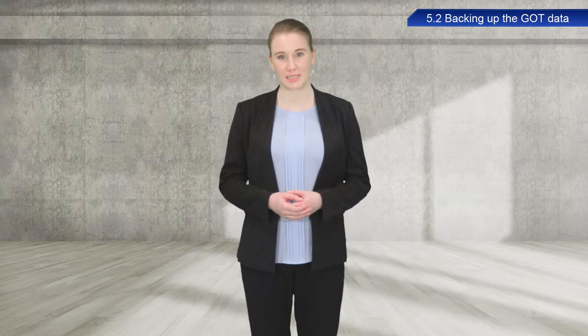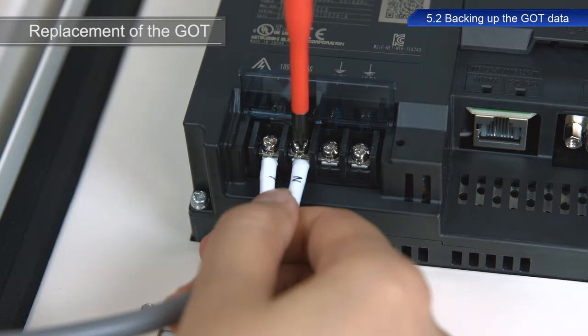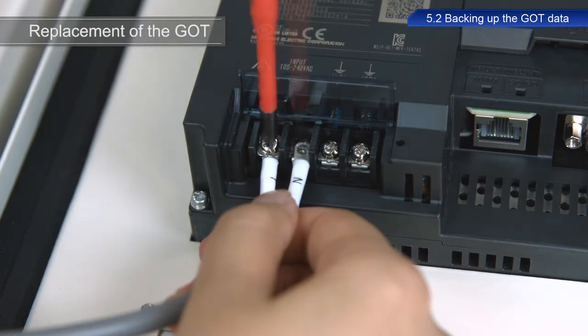Let's now replace the GOT, assuming that some accident has happened requiring replacement. For safety, you must turn off the control power before replacing devices. After confirming that the power is off, disconnect the power cables.